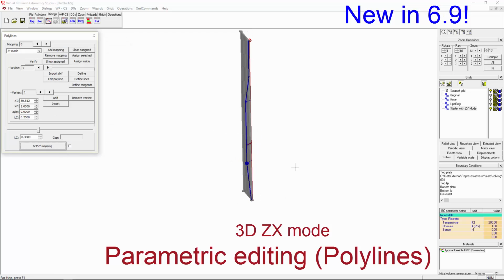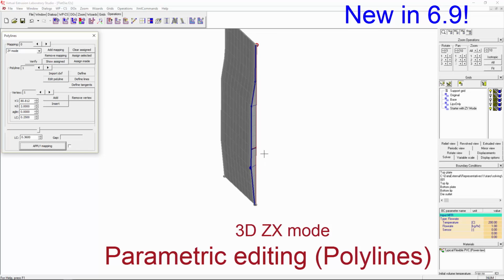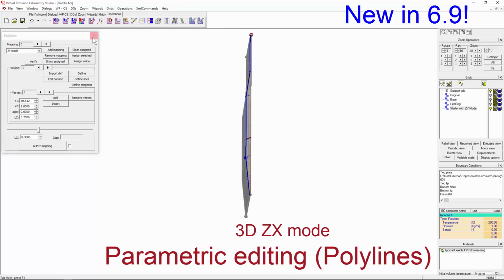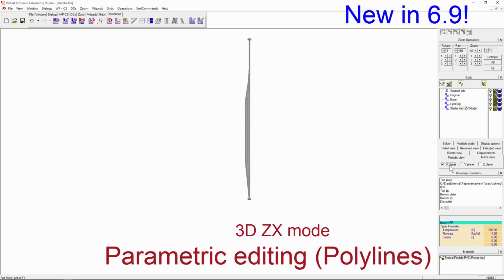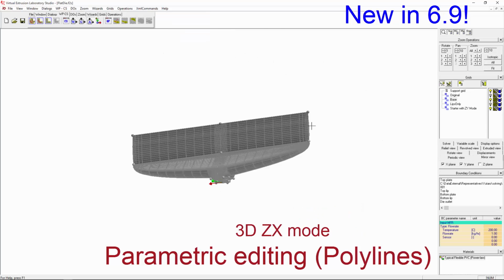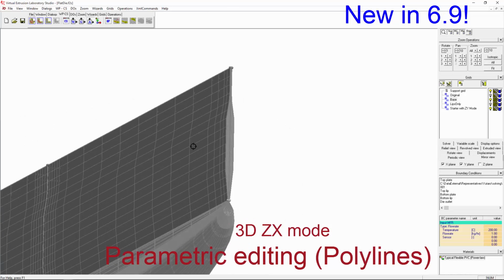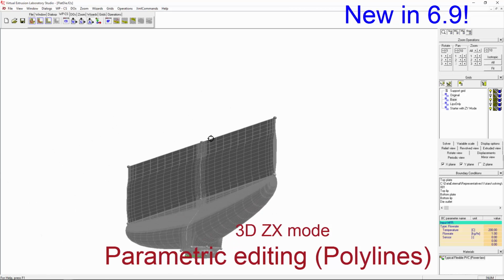When I say apply mapping, I have only one straight element, so it looks like this is not working, but now we can very easily split it into more sections. Once we're done, by applying mapping we come exactly to the shape we want for the relaxation chamber. Now if I mirror this, you will see it fits very well with our base, and we can solve it as one geometry. The main power is that I can anytime change the ellipse, the length, or the radius here. Whatever I'd like to do is really parametric.